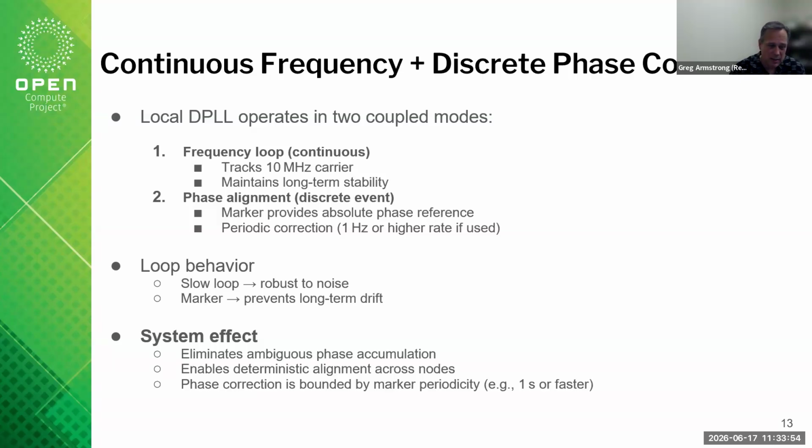So even if you wanted to independently maintain your own clock source, you could still use that marker as a very stable indicator to say, how far am I drifting with my own clock recovery algorithm that I'm using? Because maybe you're recovering a clock that is not traceable to the absolute UTC time, but maybe it's traceable to some other component, and you just want to make sure that you're not drifting over time and maintaining a stable clock recovery of that component.